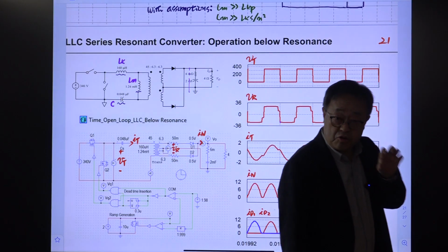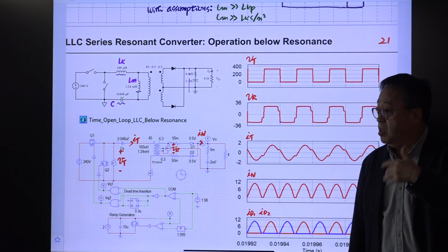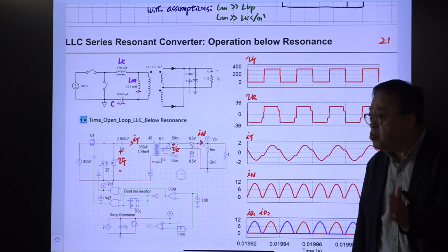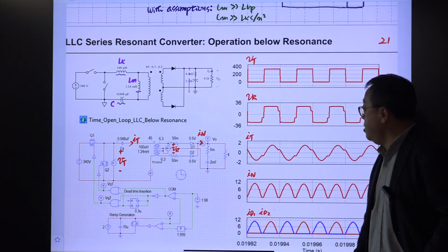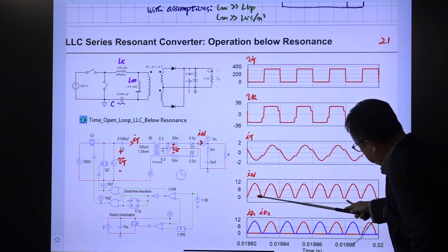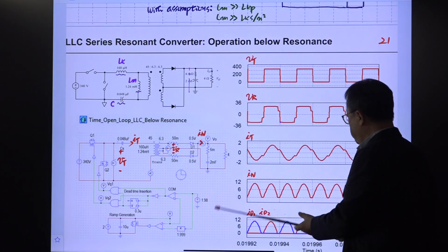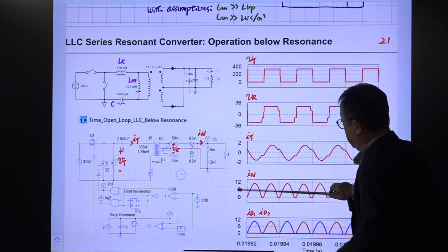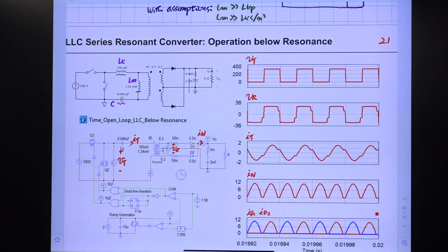We are assuming CCM operation all the time, particularly for the next coming analysis. We assume everything is sub-ideal, but in reality, there is a DCM operation here. So DCM operation is showing up here. And this is the IT1, I2, IT2, they alternate with each other to create this IN, right? And this is the operation below the resonant frequency. And this operation has some problem.